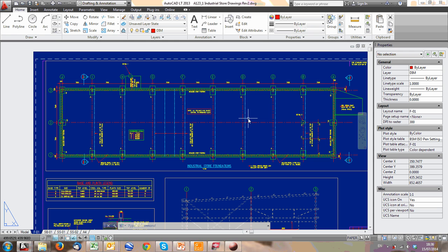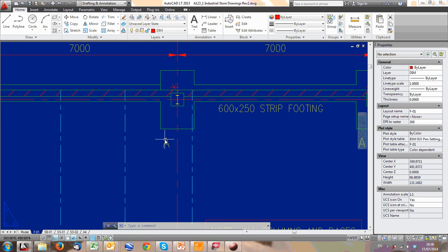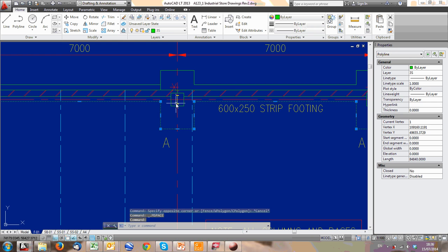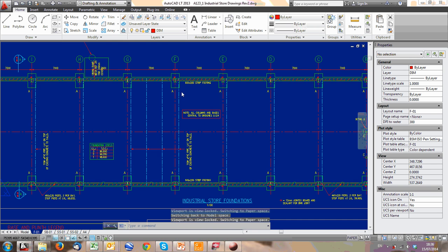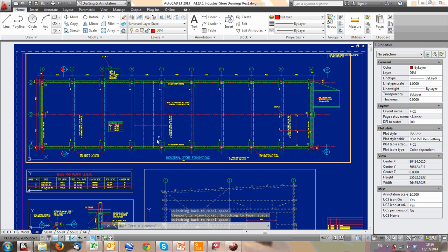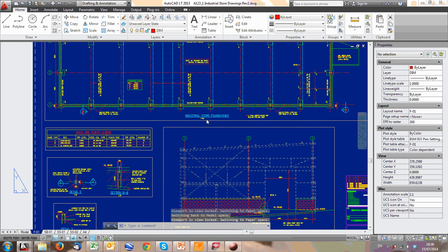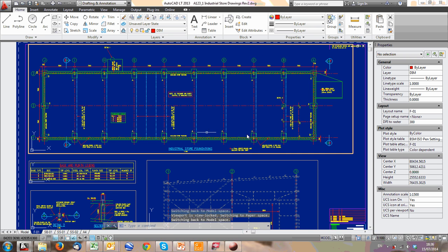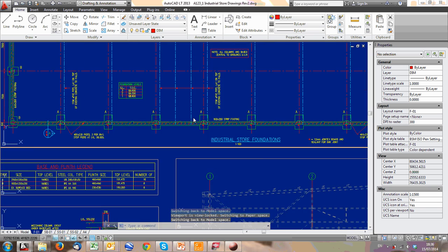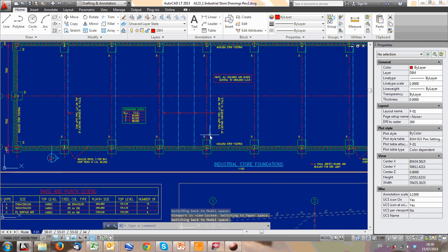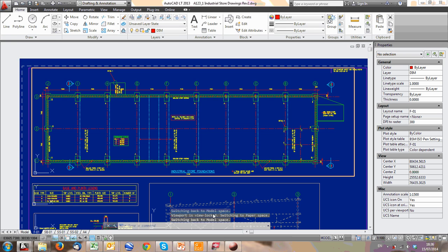And with the tools you've learned in the first two lessons, you could quite easily go through and draw those. Draw them out. If you click on those, it gives you details. You can set them as a foundation level or concrete level, or layer, or whatever is required. So that's your general foundations done quite quickly. Just make sure you set the level very carefully, as discussed previously, so that you can clear all surfaces.